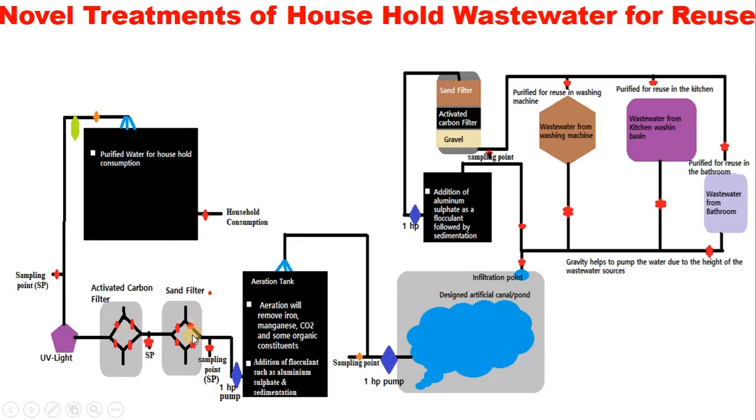You close these 2 valves here. You take a sample here to test for TDS, pH, and the alkalinity. After taking the sample and everything is in order, you close these 2 valves and open these 2 valves.